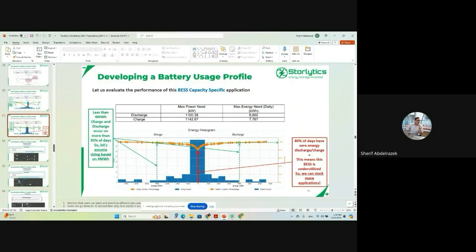All right, now shifting to the energy histogram. To be clear, all it's doing is looking at the energy discharged daily and the energy charged daily, and telling you the percentile point and the distribution of each, right? I can see from this shape, the blue here, that I have a lot of points at zero. I don't have a lot of points at higher energy capacities, which makes sense because I know we're only clipping or curtailing solar during the spring.